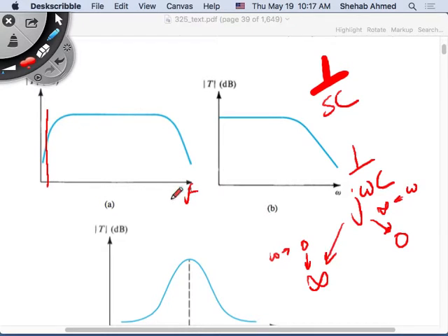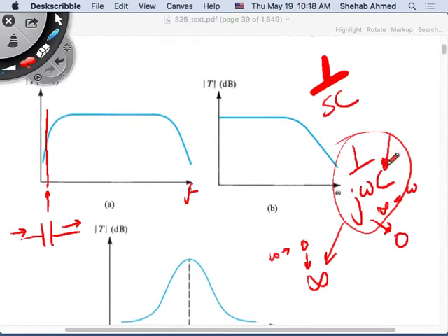Large impedance because remember, this capacitor is in series with the signal, right? For the capacitor coupled amplifiers. So I will have a large impedance to the signal. So if I don't want to have a large impedance to the signal for low values of frequency, what can I do? I can make C what? If I make C huge, yes, exactly. If I make C huge, then any value of omega, even if it's small, will pass through. This is going to be large because C is very large.